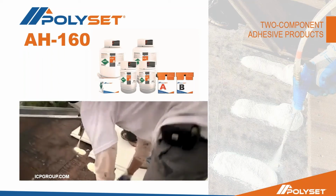So you can see from that video how quickly these installers are putting down that tile. If you have a really good crew and they're well experienced in the 2-component product, they can easily put down between 20 and 30 squares a day. Usually you'll have 3 guys on the roof, one laying the tile, one shooting the adhesive, and the other guy holding the hose there. But they can get it done pretty quickly versus, if they were having to get any nails or screws on that tile.